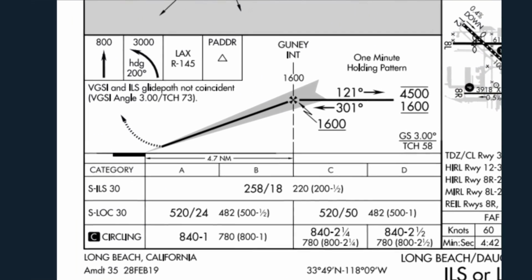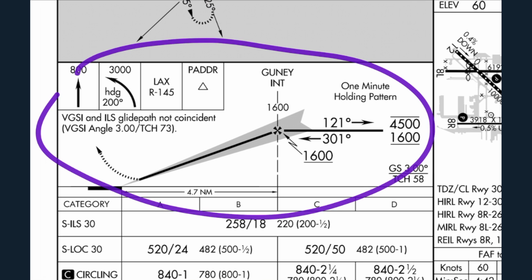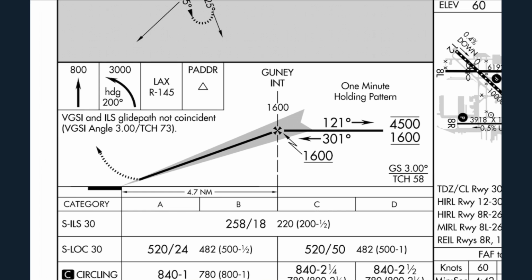The other component that's installed, usually at the front of the runway, is called the glide slope. And in this area, this is showing basically a side view as if you're standing on the ground. And this little black line here is the runway. And this shaded area here represents the glide slope radio transmission that's happening. And the glide slope provides the vertical guidance.